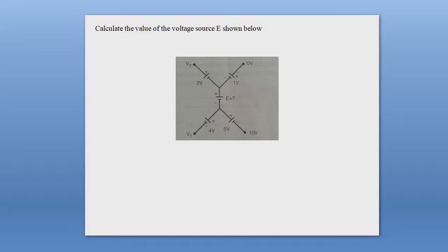You will get the expression of Z1, Z2, Z3 in terms of ZA, ZB, ZC, or the expression of ZA, ZB, ZC in terms of Z1, Z2, Z3, because we have already discussed these things for the resistive circuit R1, R2, R3. In a similar way, you can derive the expression of impedances for the two types of network, delta or pi. Okay, if you face any problem, let me know.